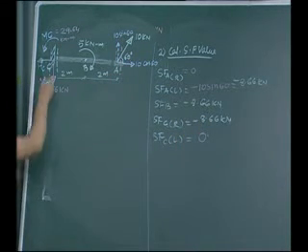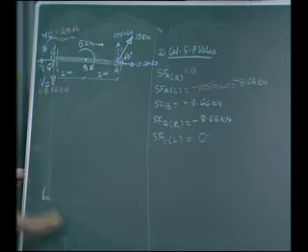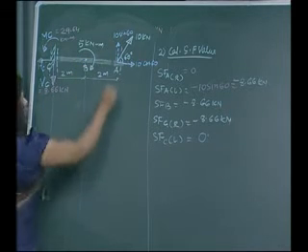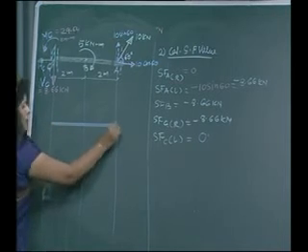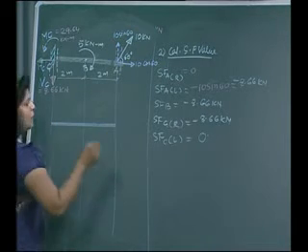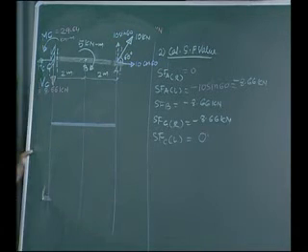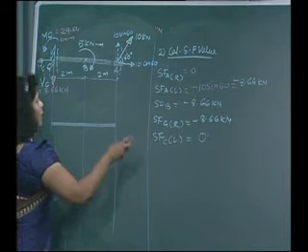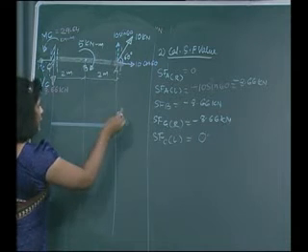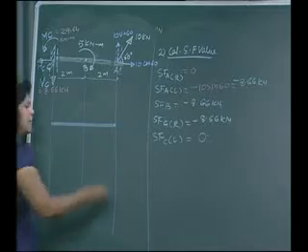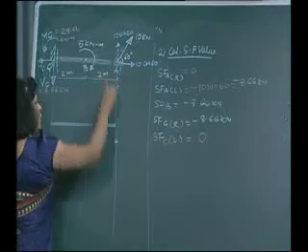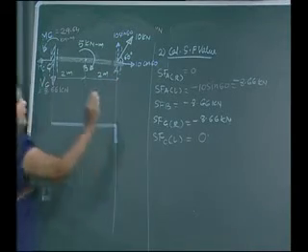Now we can take all the points where we have calculated the value of shear force and draw the shear force diagram. So it is baseline, positive values above the baseline, negative values below the baseline. We can see that we have obtained all the values as negative, right? So to start with, shear force at point A, just right 0. Shear force at point A, just left minus 8.66. As it is a vertical load, it will be a vertical line for a point load.